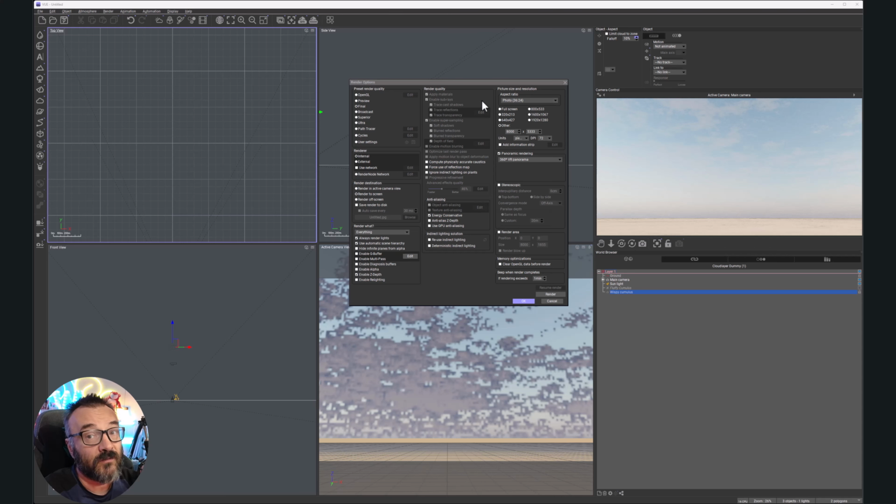That looks very cool. And next you probably want to go click final or a different quality. Again, remember, if you want to have a Cycles path tracer, which is in Blender, or you want to create with your personal adjustments, you can go to user settings and modify, but for now I'll just have it final. I don't need motion blur, so just final will work. Turn on render to screen so I can preview. I think all of these properties work just fine.